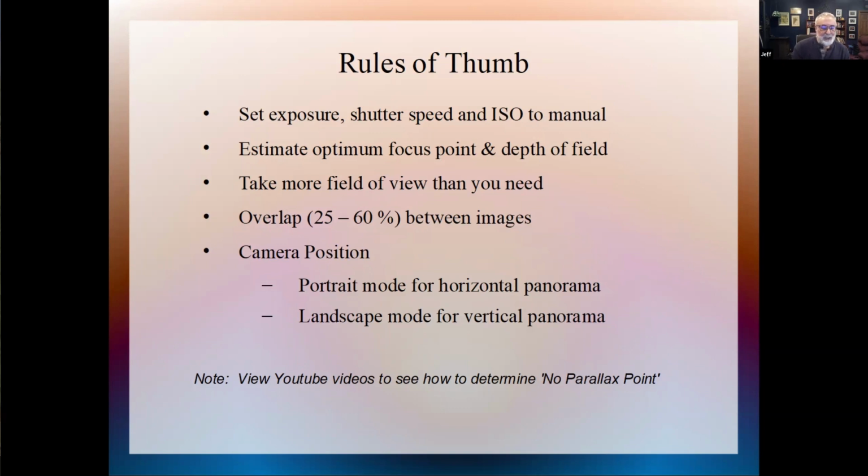So if the scene has a lot of details in it, you can get away with less overlap. If there's not a lot of detail and common points are few and far between, you want to have more overlap between your images.